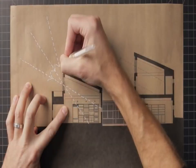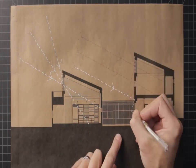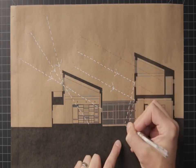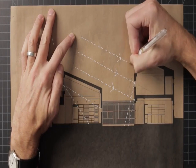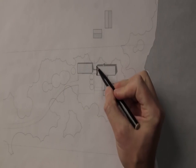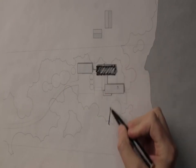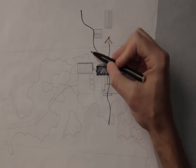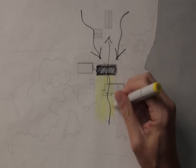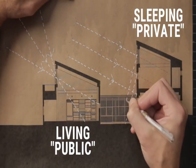As we look at the section, you can see another solar advantage of the shed roof. It allows daylight to pass by the roof form and reflect off the taller northerly wing. Because the private wing contained a lot more program than the public wing, 5 bedrooms, a laundry, a library, and a mudroom area, we had to design it as a 2-story volume. The site analysis made it clear that placing it to the northerly edge of the site would confer a number of advantages. It blocked the views to the neighboring residents, it served as a wind block from the harsh northerly winds on the site, and if we made it 2 stories tall, we could use it to help bounce light back to the northerly face of the living wing, as you can see here.